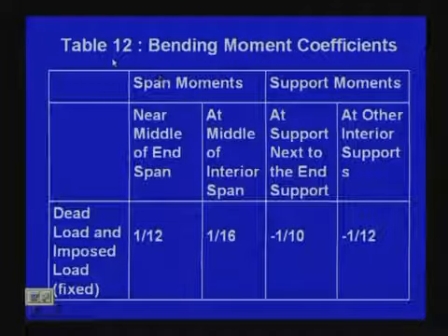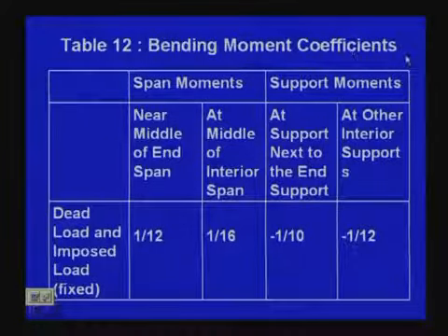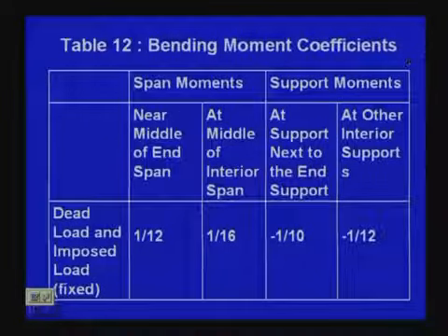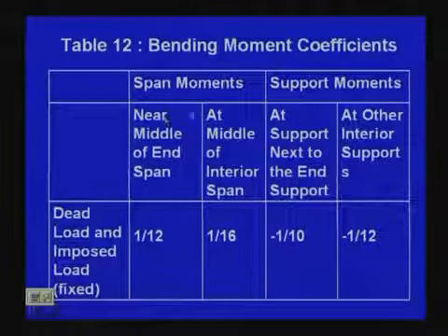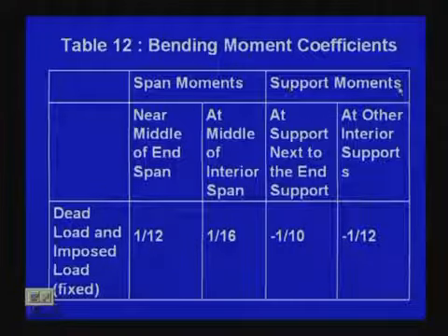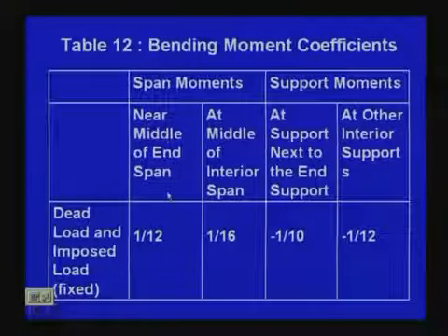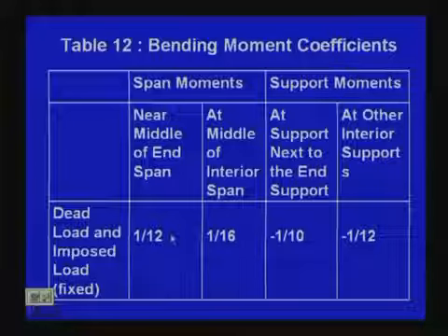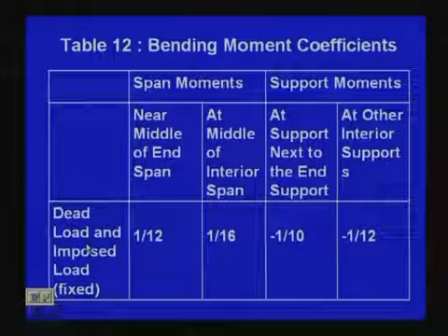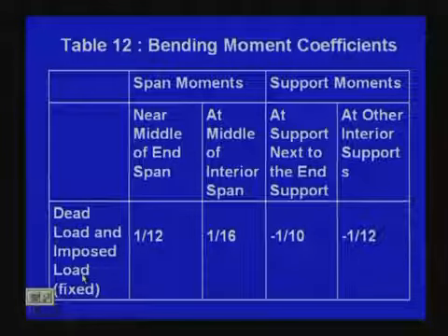So one, Table 12, that I have simply copied, gives the bending moment coefficients, but we have to use different coefficients. For span moments and for support moments, there is one span moment and there are support moments. So near the middle of the end span for span moment, we are talking about dead load and imposed load fixed.